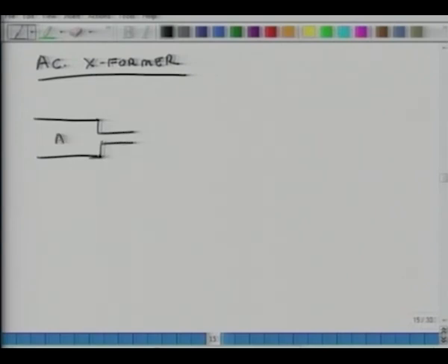So, I have area here A1, here my area is A2, my input parameters are P1 and VV1. So, again, when we are talking about acoustic elements, it is not velocity and pressure, it is volume velocity and pressure, remember that. And here my output parameters are P2 and VV2. So, the equivalence relations between two sections of this tube would be what?